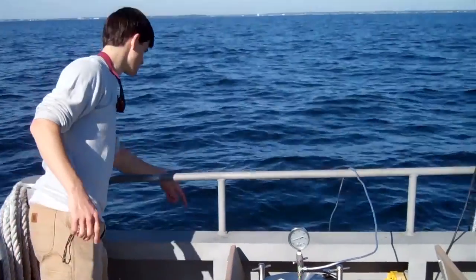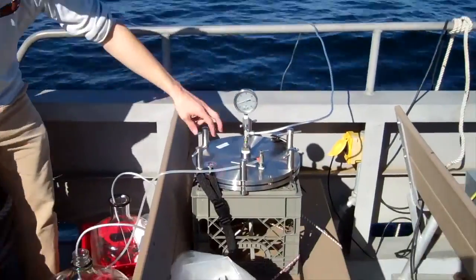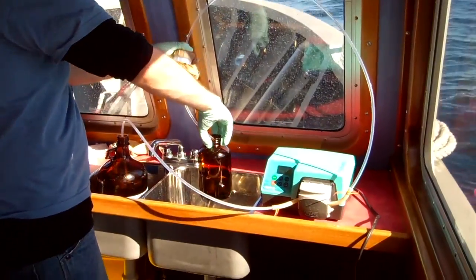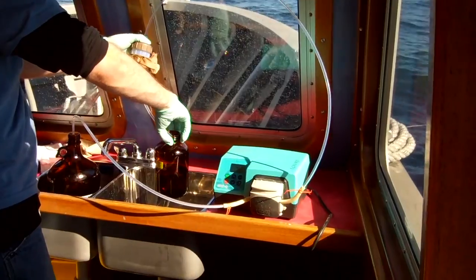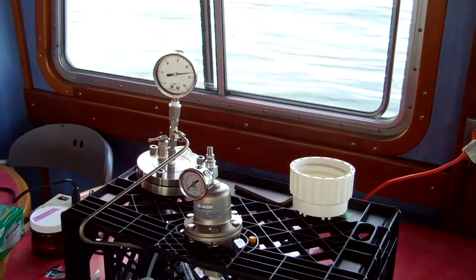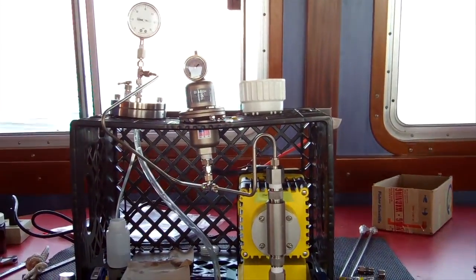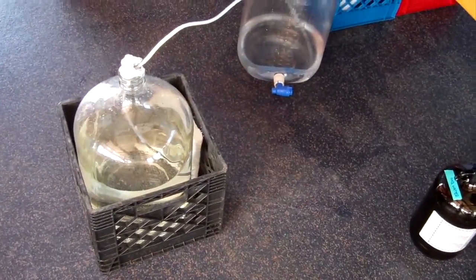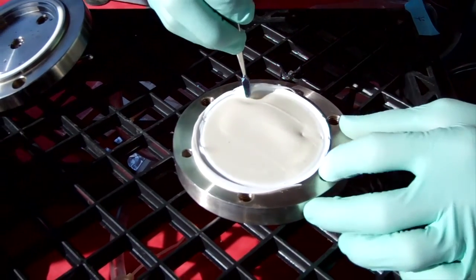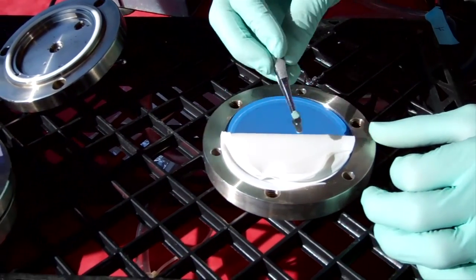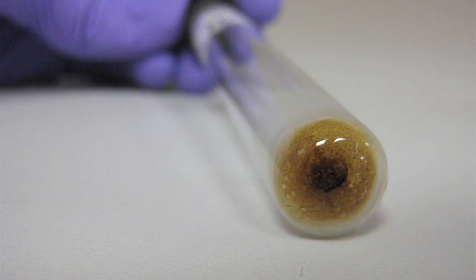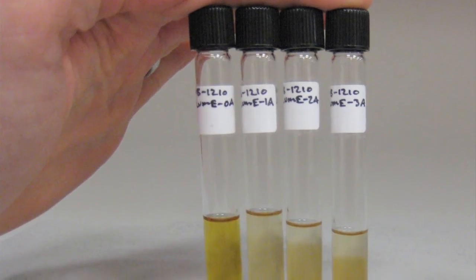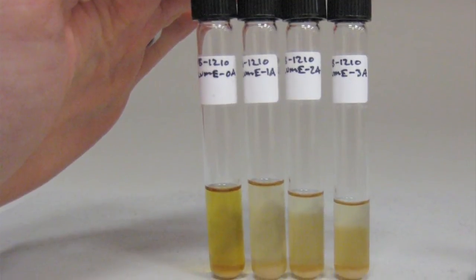Here you see me on Massachusetts Bay collecting water samples. We would collect 8 samples of 20 liters of water per day, extract and concentrate each sample down to 100 microliters before high enough levels of estrogens could be experimentally measured using a mass spectrometer. The model was key in helping me plan my sampling strategy. It turns out that this quick estimate was pretty good, and I've collected and was able to detect estrogens in Massachusetts Bay. Now I can use these measurements to refine my model.